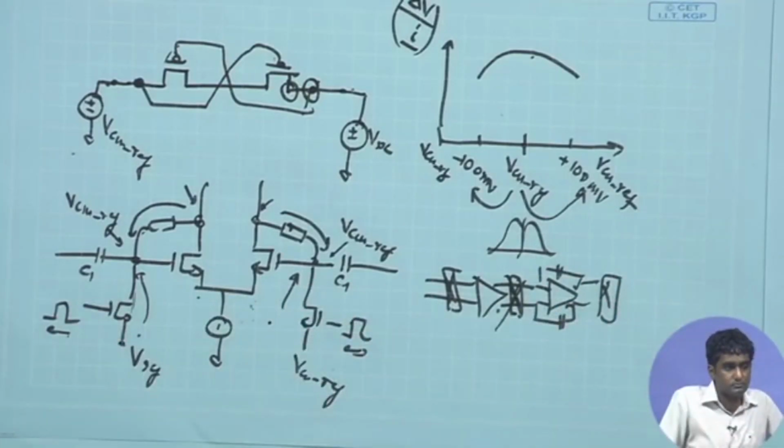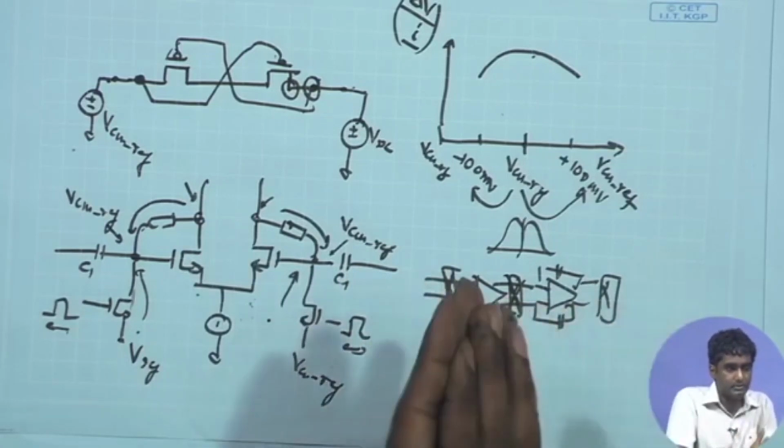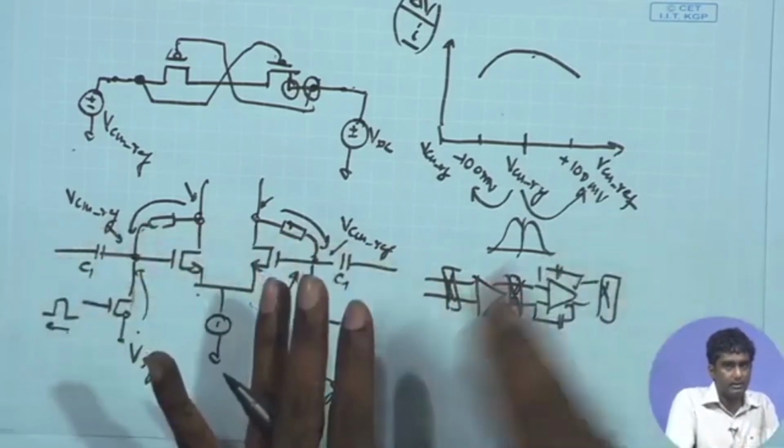But this simulation solves by using some mathematical equation, so why will it take 1 second or something like that? It's not a mathematical simulation. If you are using time domain simulation, it is basically solving matrices at every time step. Just like you do KCL and KVL, at every time step it will solve KCL and KVL, finding the next DC condition for each circuit node, and then again finding the small-signal resistance and capacitance values at every point, and again solving KCL and KVL at the next time step. So in the transient simulation it is something like a matrix simulation.